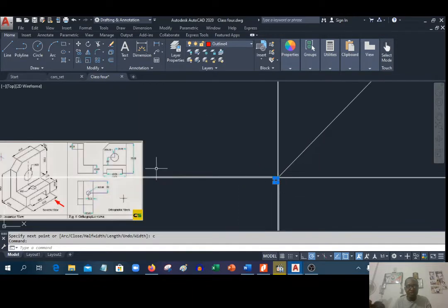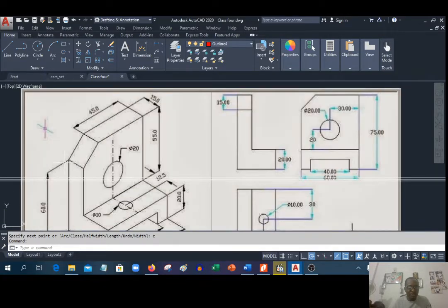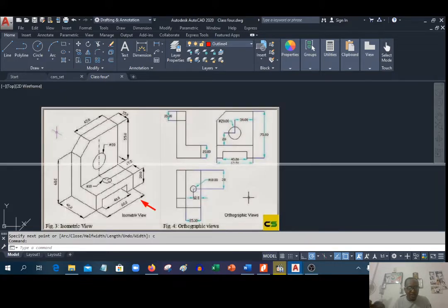Now let's come to the drawing. We have to do some calculation here, right? From this base up to 60, height of 60, that's where the chamfer started from. And the full height is 75, right? So that means 15. From this area to the top is 15. Now let's look. This one is supposed to also be 60, now it's 45. That means this chamfer is 45, 15 by 15.